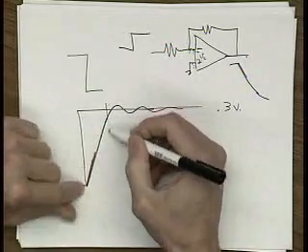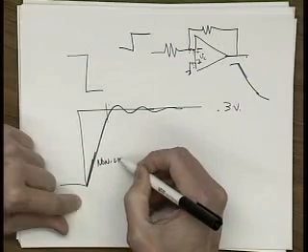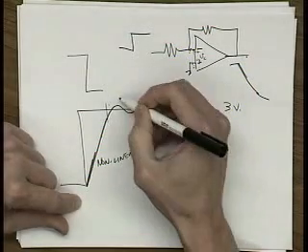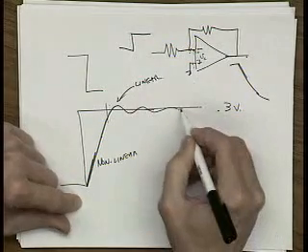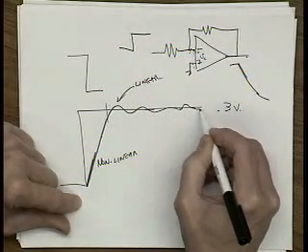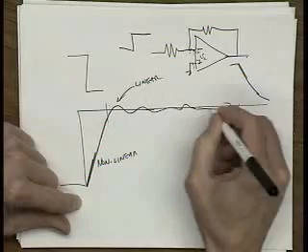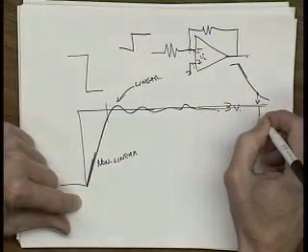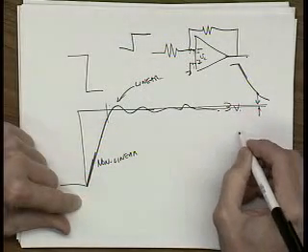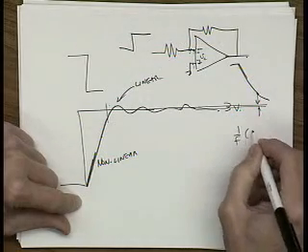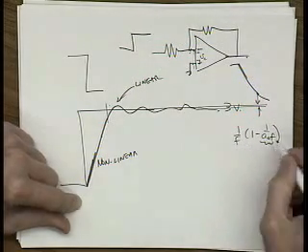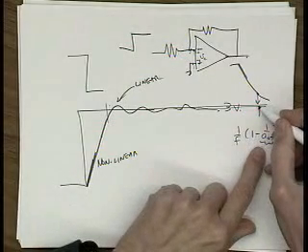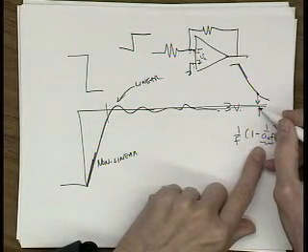So this is nonlinear period here. And here we're in a linear region. And finally, this thing will finish out, depending on its gain, to some value. And this gain, as I described, was going to be sort of 1 over f times 1 minus 1 over A0f. And so there's an error associated here, and that's where it finally gets to.